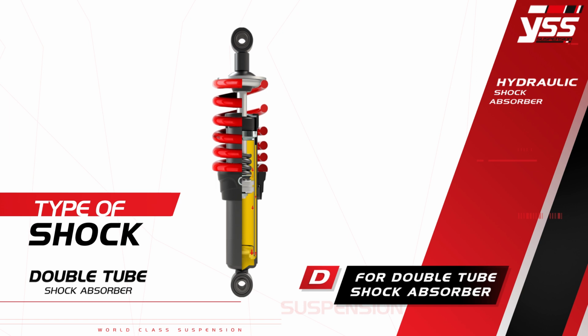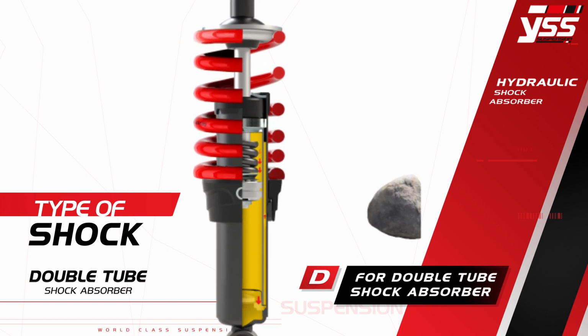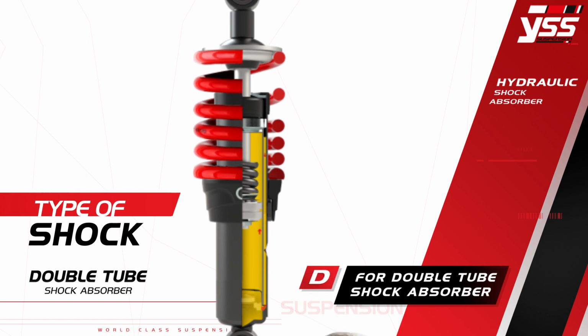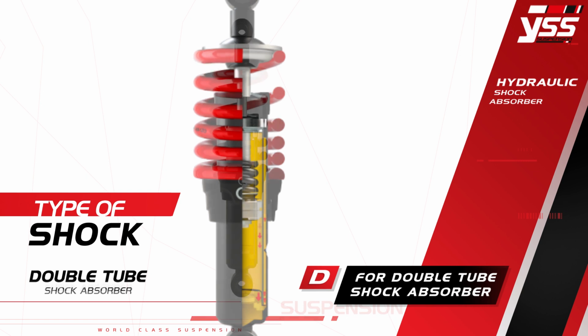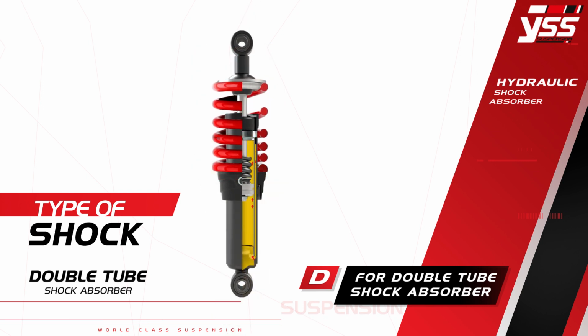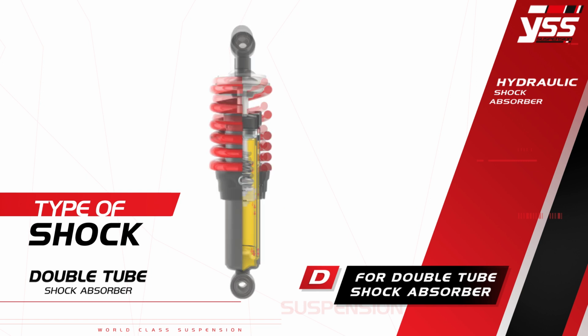Double tube, or D. This shock absorber has a double tube. The advantages are smooth ride, durable, and safe from crashing. It works with the piston moving through the inner tube. Hydraulic oil flows through the base valve, which works together with the piston set. However, its ventilation is slower than the single tube shock absorber, and the price is higher. Plus, it has to be installed with the shaft at the top.